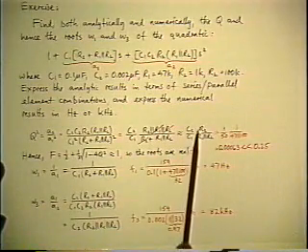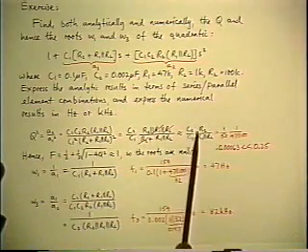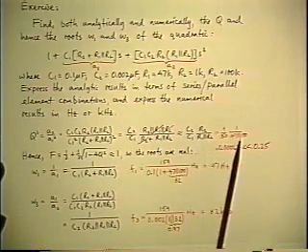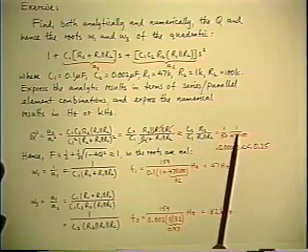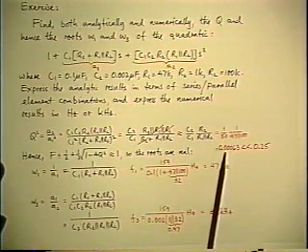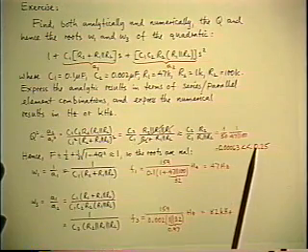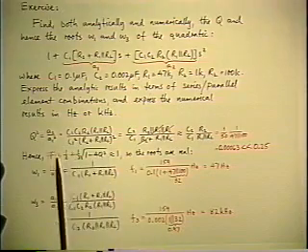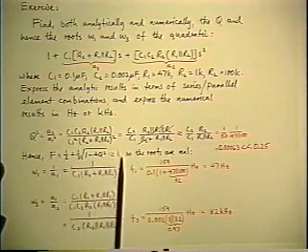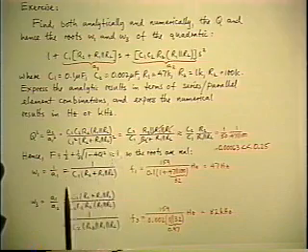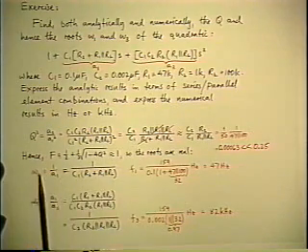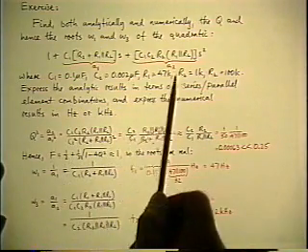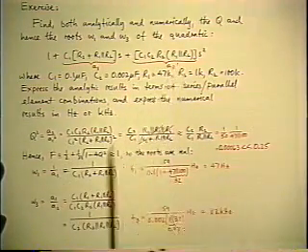And you see immediately that because C1 is 50 times bigger than C2, and R1 parallel RL is a lot bigger than R2, then Q squared is indeed very small, and Q is much less than 0.5. Very much less. So to a very good approximation, F is equal to 1, so you can use the real root result, which is one of the roots is simply 1 over A1, and the other root is A1 over A2.